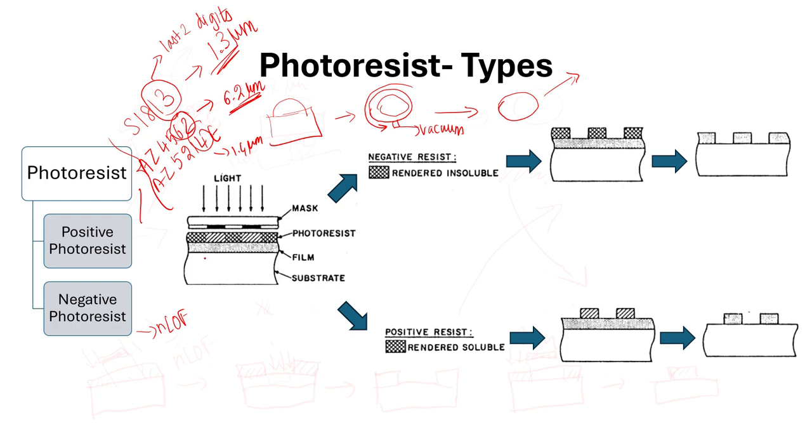So what is positive photoresist and negative photoresist? Positive photoresists are chemicals which, if exposed to light of a particular wavelength, the exposed regions will dissolve easily in the developer. Any bases we have, it will get dissolved easily. But in the case of negative photoresist, the region that is getting exposed will polymerize and harden. The remaining region that is not exposed will get easily dissolved.